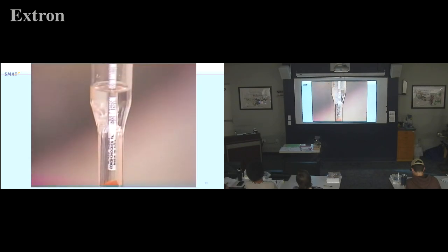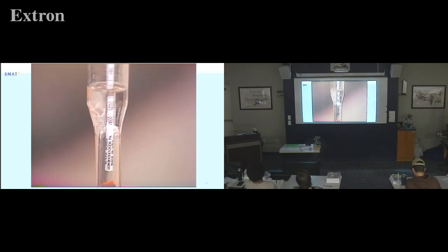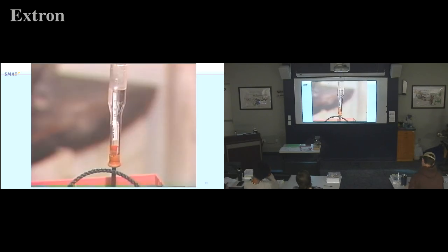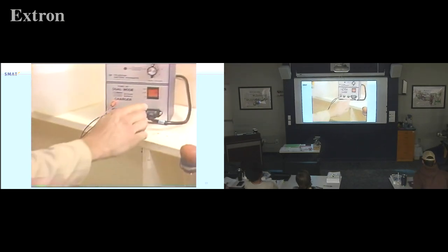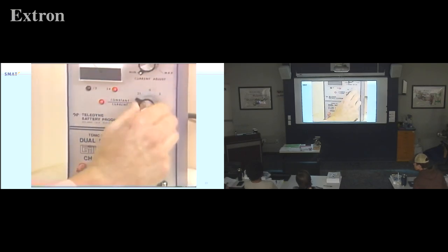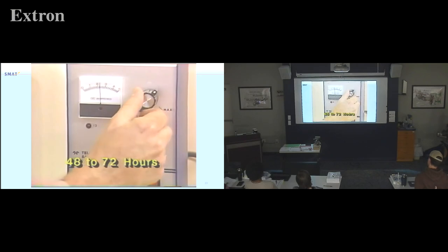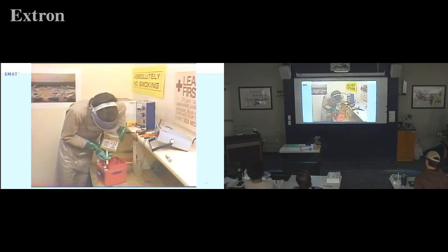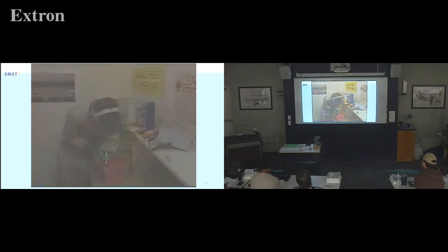If the specific gravity for any cell will not come up to its recommended operating range, the battery may be badly sulfated as a result of being unused or may have been completely discharged. Continue charging at 10% of the 1-hour discharge rate until the specific gravity reaches its normal operating range. This procedure could require 48 to 72 hours. Adjust electrolyte to the bottom of the split ring, being careful not to overfill the cell.